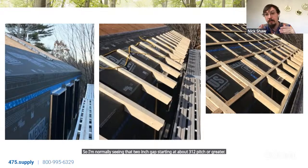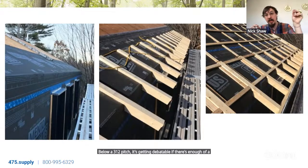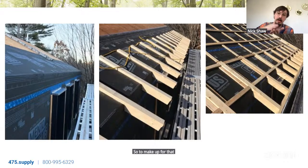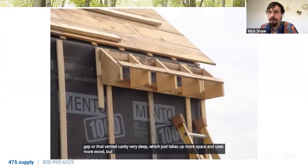Below a 3/12 pitch, it's getting debatable if there's enough of a pressure differential from the eave to the ridge to adequately vent. So to make up for that pressure differential, people are making that drainage gap or that vented cavity very deep, which just takes up more space and uses more wood, but is otherwise a great approach.